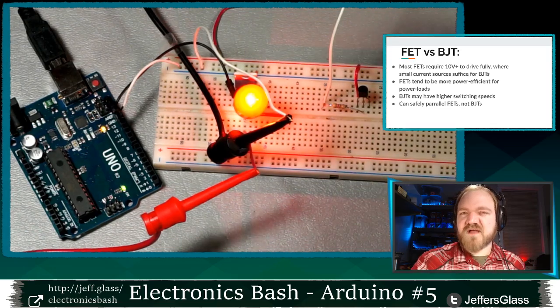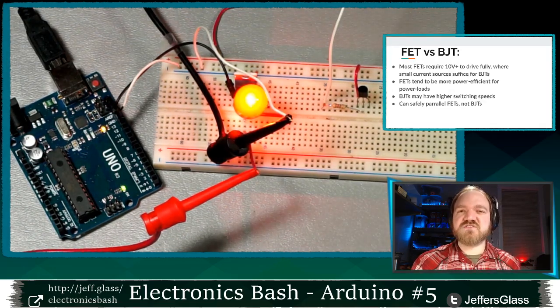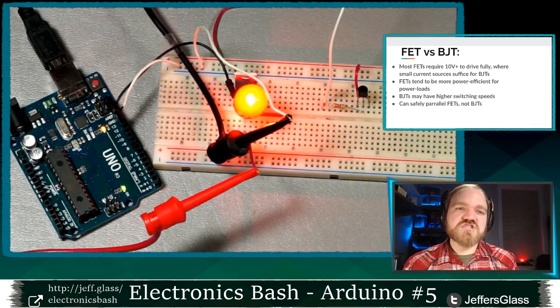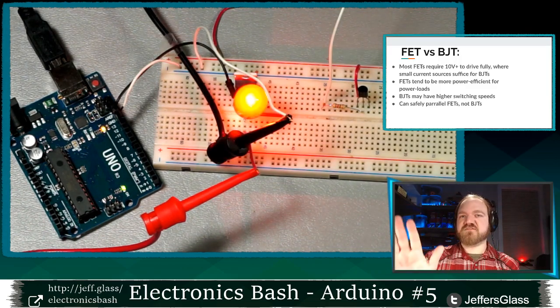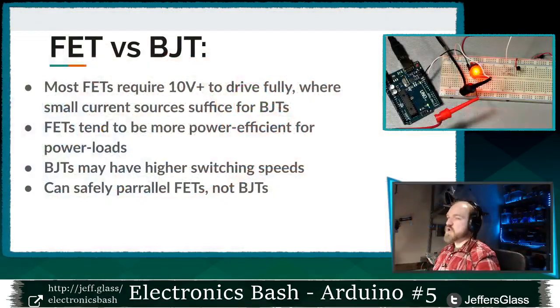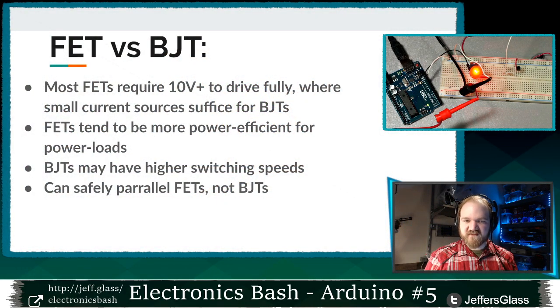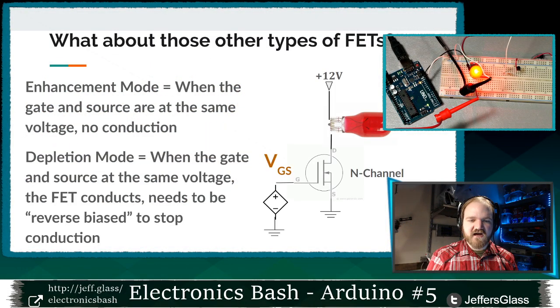That's not true of bipolar transistors. They don't tend to do that same kind of load sharing. So when you're thinking about really high current applications where you need to put multiple devices in parallel, FETs are preferred over BJTs for that kind of application, if that makes sense.